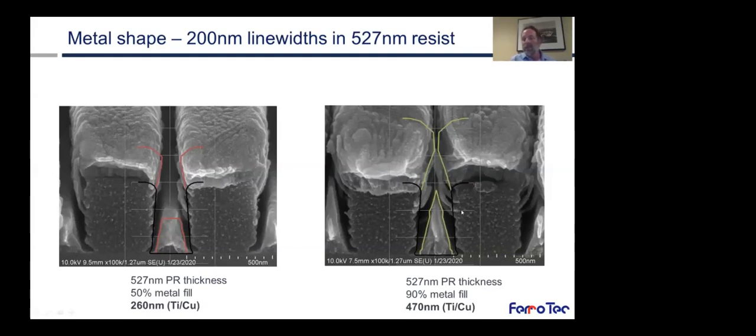So we can see from this that if we were to increase the aspect ratio further, we wouldn't be able to increase the metal thickness anymore. This metal occlusion would begin to limit us. Now, of course, we're already getting the limit of the photoresist anyway, so there wouldn't be much path that way directly here.